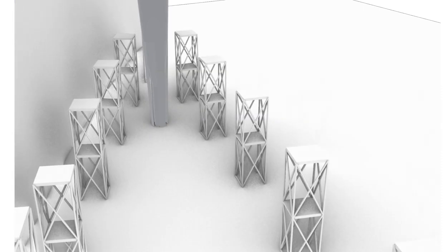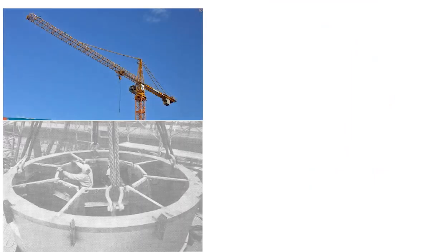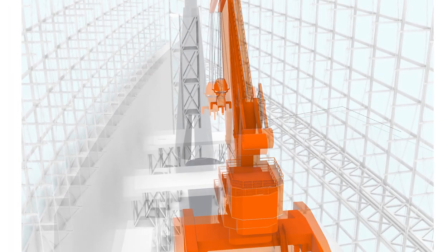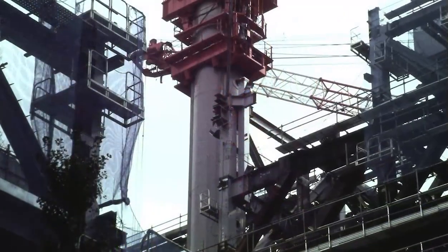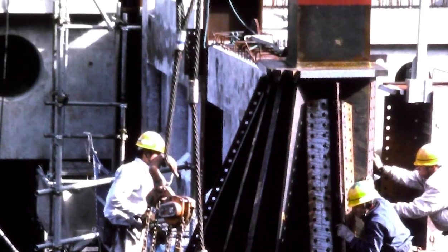The construction from the 1st to the 9th section involves stacking steel frames with a hydraulic crane and alternating with concrete pouring using tremie pipes. As the construction reached higher levels, the hydraulic crane became impractical, and the traveler crane was used to complete the installation from the 10th to the 17th section.